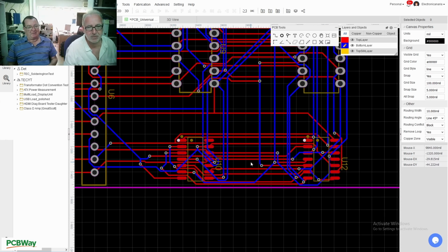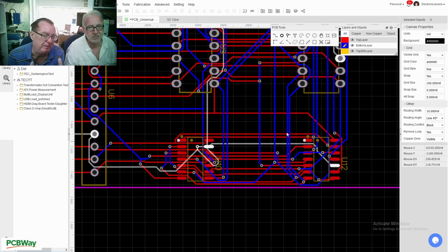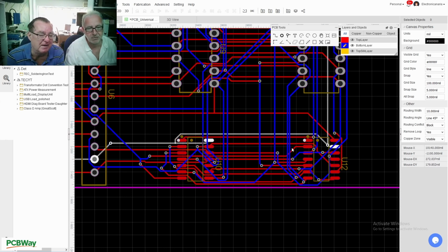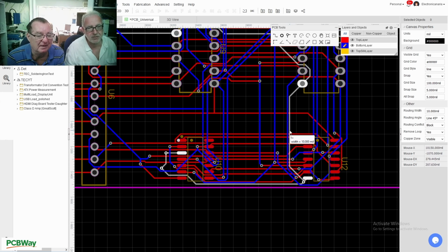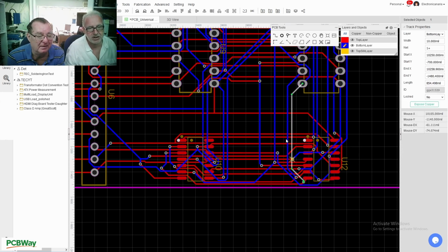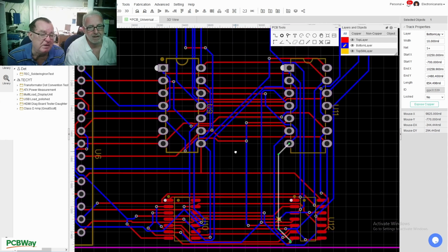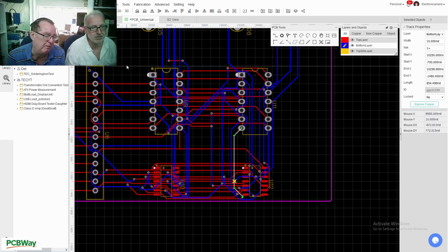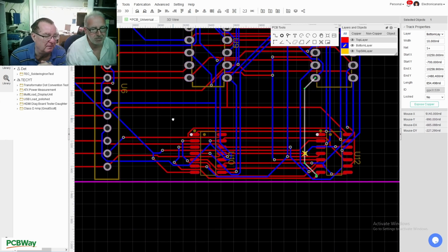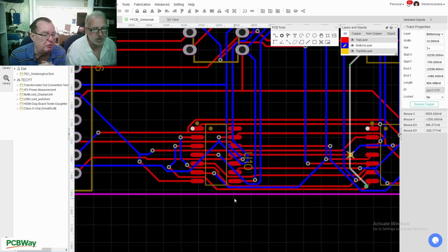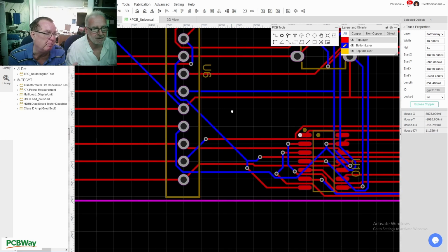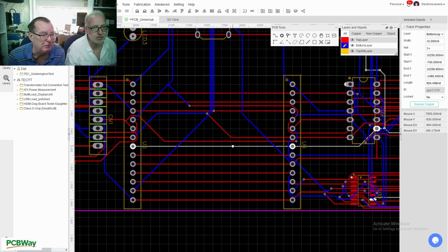Well, what effect would this have on the performance of the device? Look at this. Look at these. Yeah, I see. The first thing I want to do is fix that, because I don't need this tight spacing here. So maybe you can use the auto router and just tidy it up a little bit. I mean, will you take on board what I'm saying, because it's all very low frequency and there's no current? Yeah, probably, but oh man, look at this. I mean, the current limiter sets the maximum current for the whole board at 50 milliamps. It can't draw more than that.